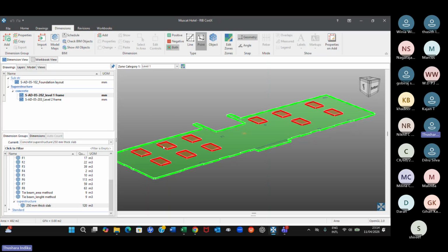So for that we have deducted, and you can't apply that principle here. But if you have a genuine cutout, a shaft, which is less than 1 cubic meter of volume, then you don't have to deduct it as negative. You can follow measurement rules as they are. That's why you have to be a smart QS.